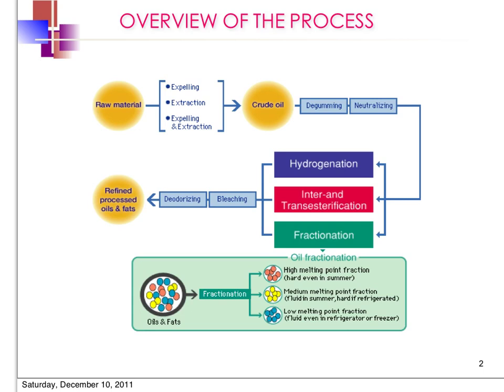For this purpose, we can use two types of extraction. We can use an organic solvent. This is solvent extraction, which will extract the fat or the oil from the fruits or from the seed. And another process is without using solvent, which we call physical extraction. Usually this uses a mechanical press, for example a screw press, to expel or extract the oil physically out from the seed or from the fruit.